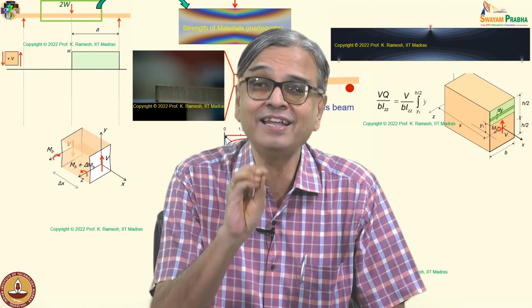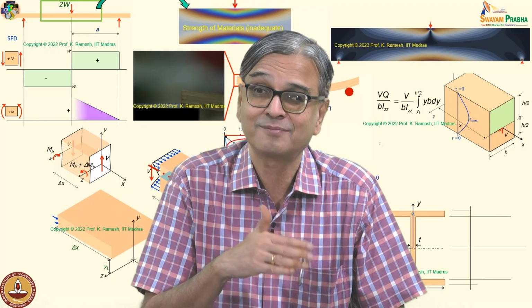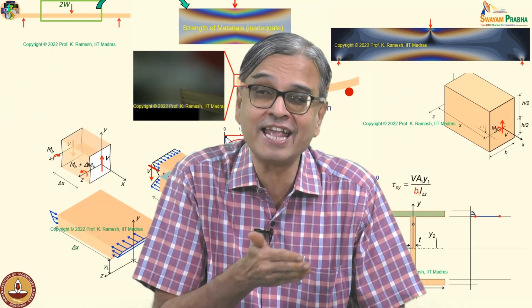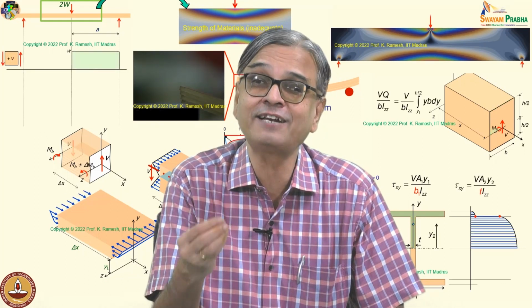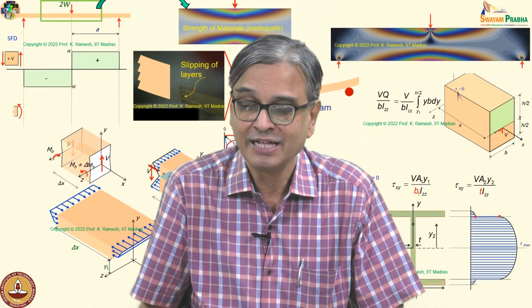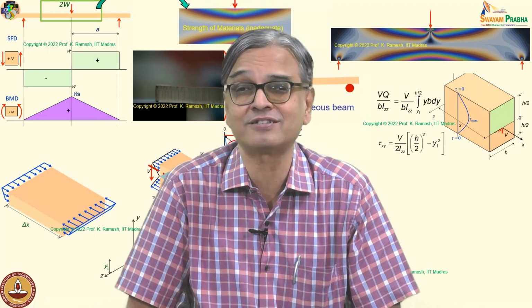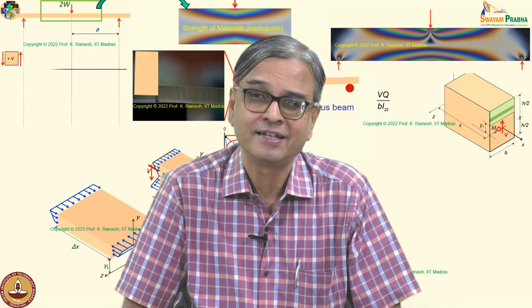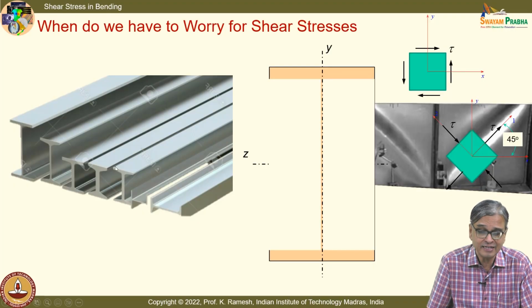It can be very damaging to you if you do not recognize it is another avatar, because we have seen when you look at the Mohr circle, you should recognize the same stress tensor can appear in different ways. So, it can precipitate failure in one form, but you can also have failure in another form. I do not know how many of you have noticed it. See, the moment, this is why people fear bending, I will have tension as well as compression, even if I take a simple rectangular beam, okay.